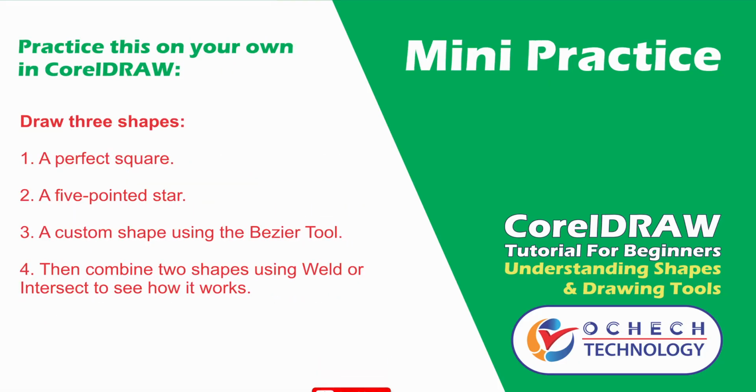Now, this is a mini practice for you. I want you to draw three shapes. One, a perfect square. Two, a five-pointed star. Three, a custom shape using your Bezier tools. Then combine two shapes using weld or intersect to see how it works.